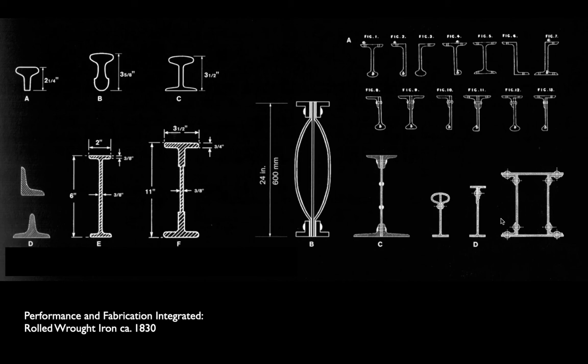It's a natural shape, of course, for a railroad rail. It has a bulb on top and the spiking flange on the bottom. But you can think of those two as if they were an I-beam. And the strength of locomotive rails are one of the things that leads them down the path to the modern I-beam. On the top right, these are deck beams for ship construction. And again, it's almost like you flip that around. You've got the bulb on the bottom now taking the tension, and the flange on the top that allows you to attach decking to it.